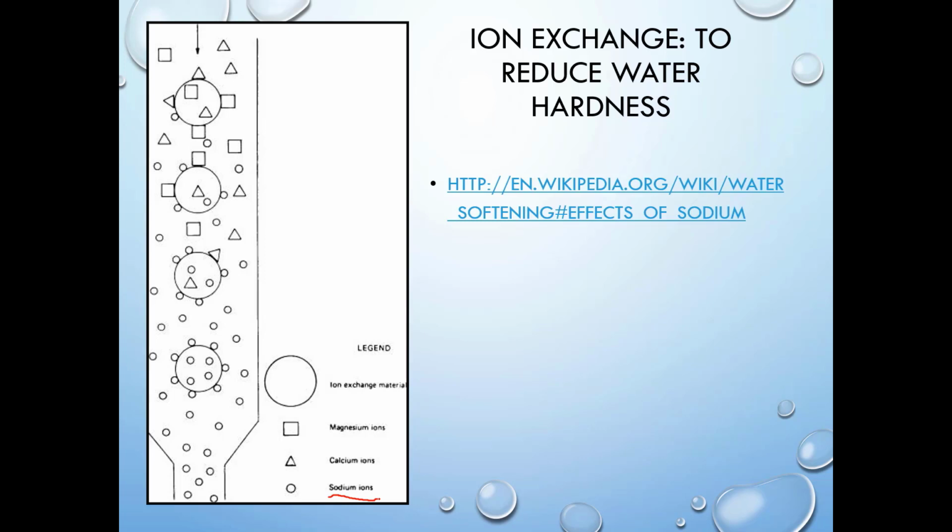The main disadvantage with ion exchange is really all of that sodium that is being released into your water. Again, I told you it doesn't taste particularly salty, but the problem is that the sodium tends to make other stuff dissolve. I don't know if you remember from the lecture 5 series, how all of that extra chloride in Flint's water tended to make the iron dissolve? Well, all of the extra sodium that you could be releasing into your water can make other ions dissolve as well. And that may not be what you want to be drinking necessarily.